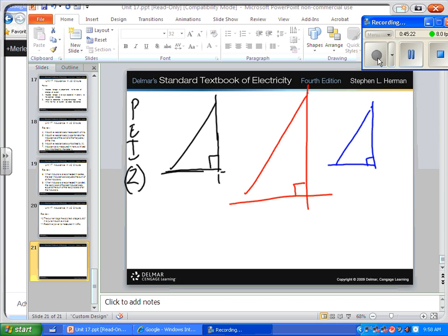We're going to say that this is a 120 volt single phase motor. So our total voltage is 120 volts, right? Do we see that? Okay. Now, let's say that if we take this motor and we read the pure DC resistance of the windings, we get 20 ohms of pure resistance. Now, we're always going to put these triangles, where I'm starting a little early on this material, but that's okay. We're going to work on this a whole lot. We're going to work on this all semester, okay?